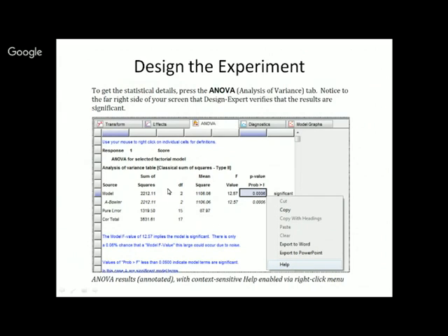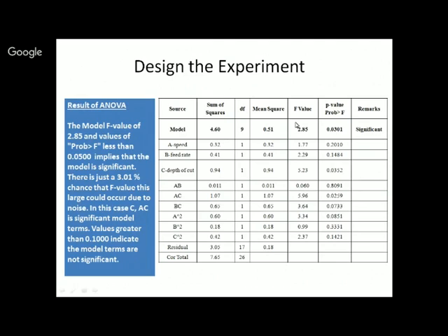Basically these are the calculations, but the software calculates and tests the ANOVA itself. You have to do nothing with that. In my case, it gives the p value as 0.03, and my quadratic model for the surface roughness is significant. From the F value you can see that 5.23 is the maximum factor. That means 5.23 corresponds to my depth of cut.